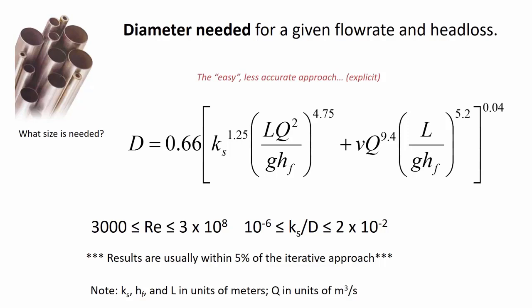There would be 150 millimeter pipe diameter, then you'd have to go to a 200 millimeter pipe diameter. And so if this is saying that you need 0.175, it doesn't really matter because you are going to have to step up to the next larger pipe size anyway. But when it would matter is if you did this shortcut approach and it said, let's say you need 205 millimeter pipe, but you really could have gotten away with one that was smaller, when it artificially bumps you up to the next pipe size when you maybe didn't need it. That's when that 5% is going to end up having a difference.